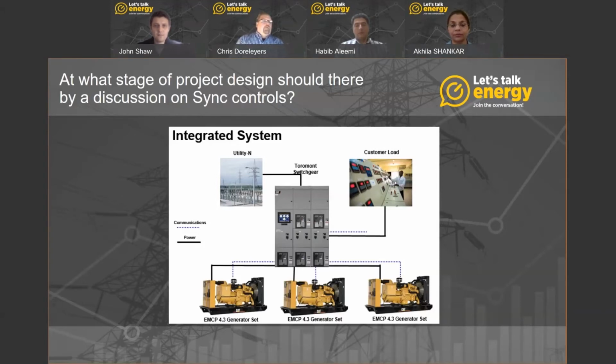On the prime power side, the focus shifts to running and trending. So looking at the coolant system, looking at, let's say, your turbo temperatures, other temperatures in the system, your fuel system pressures and so forth. From there, one can take a look at long-term trending analysis, because these things are running continuously and you can foresee potential problems.